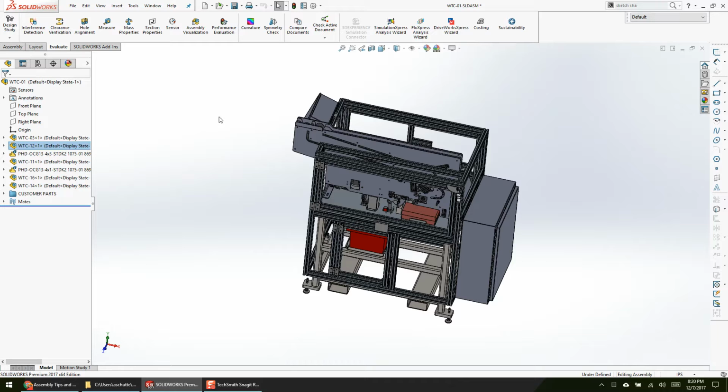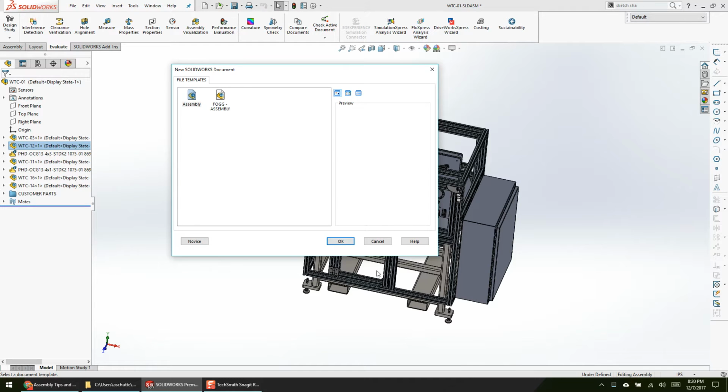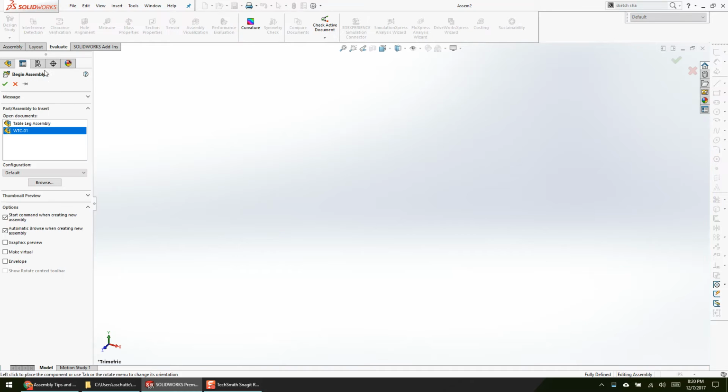Doesn't it only fix it if you check the green check mark? No. So if I take this and I put it in an assembly, here's the difference. If I click on the green checkbox, it'll put it exactly on the origin. And that's the other argument, that if I do that, then it's on the origin, and then you have no argument. And I'm like, really? How many people do that? In a company, I've never found everybody does that consistently. So now you have inconsistency. Now I'm going to assume because it's fixed, it's on the origin, and it's not. And I'm going to mirror my plane, and I'm going to make a $50,000 machine wrong because it's off by a quarter of an inch.